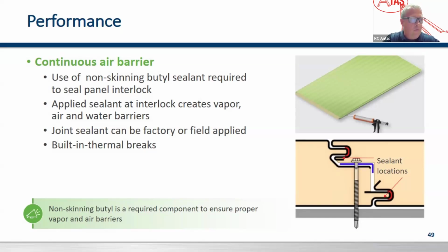So when it comes to energy conservation, thermal performance of the building, and the overall comfort of the building, we're basically making a building that's a large cooler. One of the most common applications for insulated metal panels is cold storage or refrigerated buildings because of the energy performance and the high R value. So any type of building where you're really looking for accelerated energy performance, insulated metal panels would be a great choice.